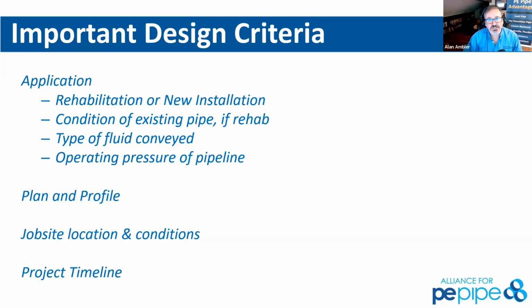We're looking at condition of that existing pipe. Is it necessary to be able to find that condition? In some instances, for pipe bursting, we don't necessarily need to have all that condition, as long as we can stick those quick lock rods through that pipe, attach on to the expander head, and break that existing pipe, we'll be a happy camper.